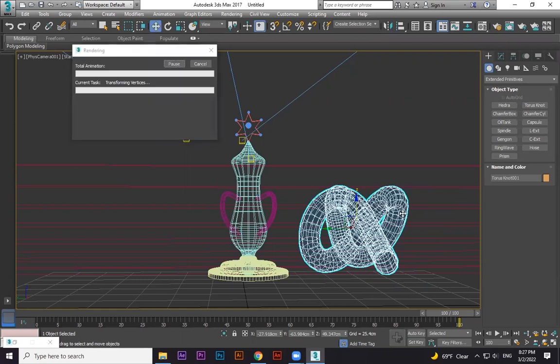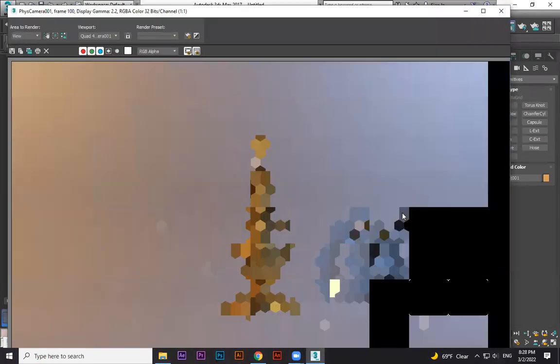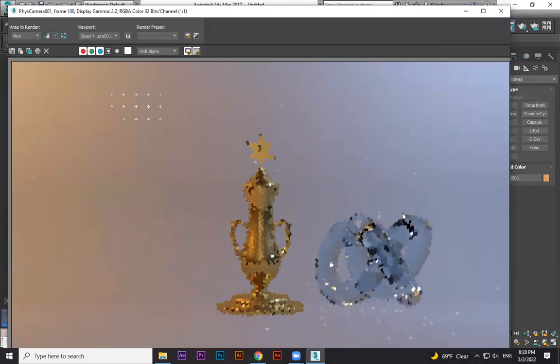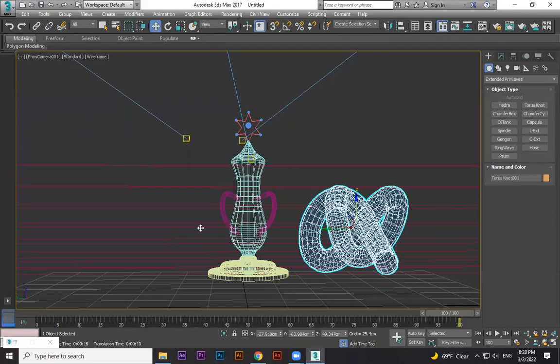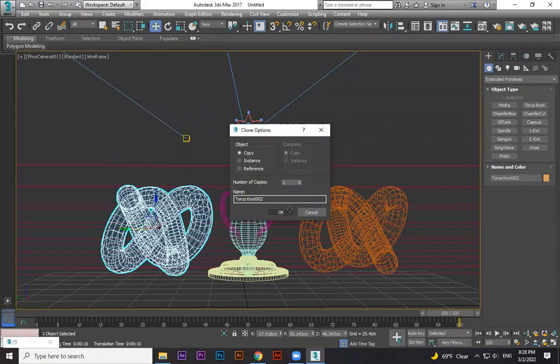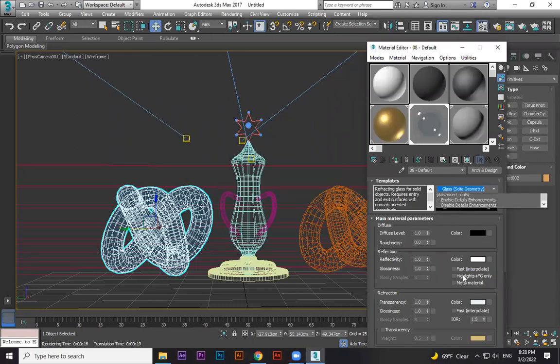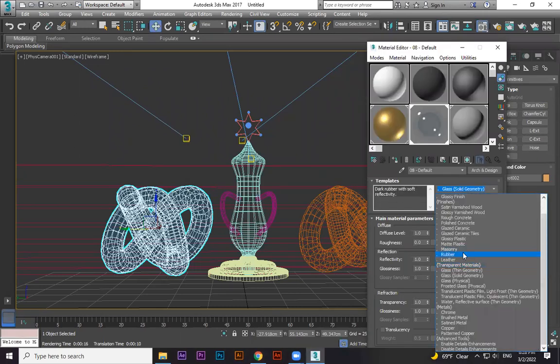So once you have this lighting setting, try different materials. I told you yesterday, lighting is very important to the material. If your lighting is not good, you cannot see the right result. Now see, good lighting is this. See how perfect the glass is. Can you see the reflection coming? Yesterday when you were doing that, the perfection was not there, right? Because when you do proper lighting on it, that's the reason I've taken this lighting today, just to understand the material idea.